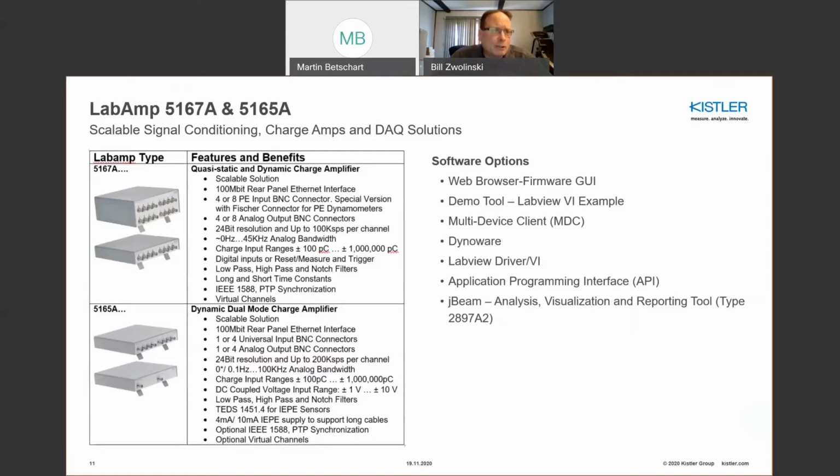So what this enables you to do is get a complete solution and collect your data, either analyze it using one of your analysis tools or perhaps one of the software options that are offered with these units. You can perform your analysis. But some of the key features of these data acquisition systems is 24-bit resolution, upwards of 200 kilosamples per second per channel, all simultaneously sampled.